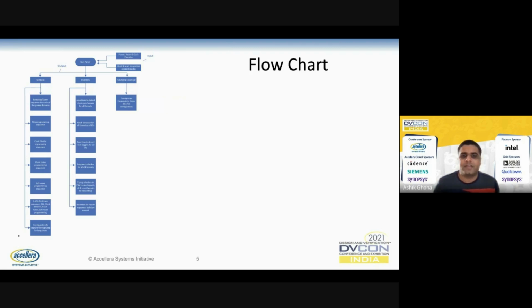For SoC level verification, we need C APIs for all of this configuration. For that, it generates C APIs for PLL programming, clock gates, resets, and clock dividers. For JTAG also, it generates constraints and a programming sequence for the JTAG chain. Under checkers, we are generating assertions to detect the clock and reset fan out toggles. To catch glitches, we have a glitch detector bound to each clock and reset fan out.